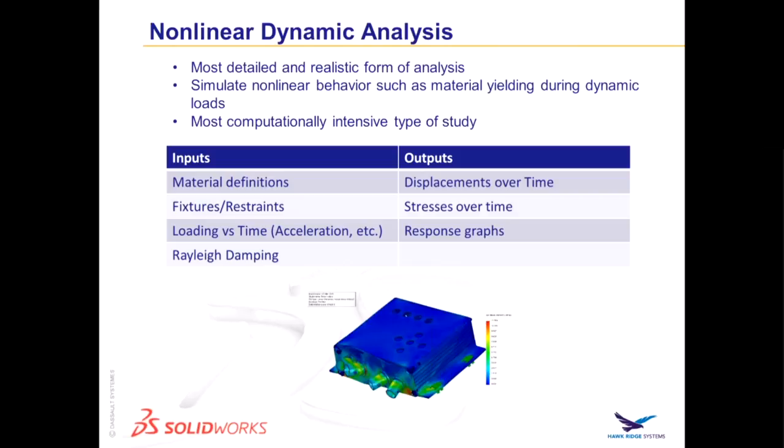And if you're in any way familiar with the drop test study in SOLIDWORKS Simulation Professional, that actually is a type of nonlinear dynamic analysis, although it has been streamlined greatly to only account for one type of problem, which is dropping a product onto a flat surface. So if you think you have a situation where your product needs to undergo something like a drop test, but it's a little different, for example, you want to simulate another object impacting your product instead, or maybe a projectile of some kind, or again, pieces of the product permanently deforming or contacting with each other, then nonlinear dynamic analysis is what you'd want to look at.